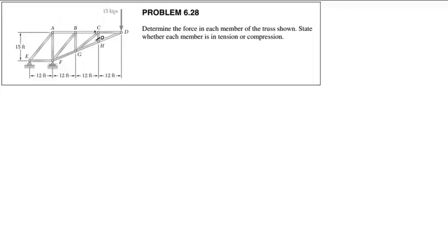Now, let's look at joint C. With this thing out of the picture, there is now nothing to resist a load in this member. Again, by joint C, therefore, this is a zero force member. Again, on joint C, if D is now out of the picture, so you can sort of imagine covering this one up with your thumb, then I now have two collinear members with a third going into that joint. So this is a zero force member. Which are the collinears? BC and CD.